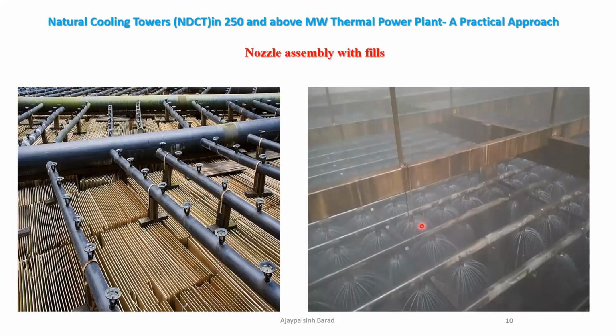Here you are seeing the nozzles at the bottom side, and here the nozzles are at the top side. So below these nozzles are the sprinklers, and the hot water is coming from the bottom, and while flowing upward it comes in contact with this water spray, and all the water particles almost get cooled and fall in the sump.